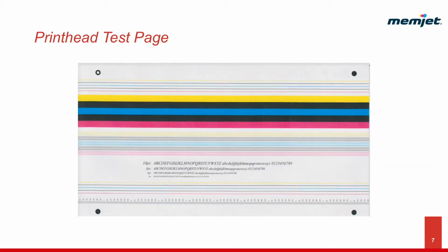To bridge the customer images to the diagnostic images, memjet has developed a printhead test page. This page is embedded in firmware, so by default already available to your field install base. Check with your supplier, but this may also have a detail page that prints out usage information for the printhead. So let's take a look at what it has to offer.